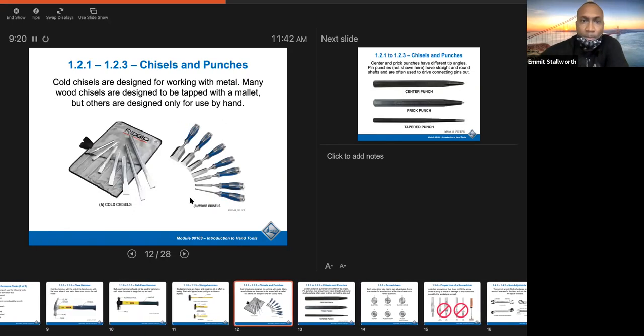And these are your chisels, guys. This is a nice little tool to have, especially if you guys are doing trim carpentry or putting doorknobs on, something like that. Chisels are good. Sometimes, I don't know if you guys ever looked at the strike plate, where you close a door, you have what they call a strike plate. It's where the door latch connects to the jamb. Sometimes those things need to be chiseled out or re-chiseled.